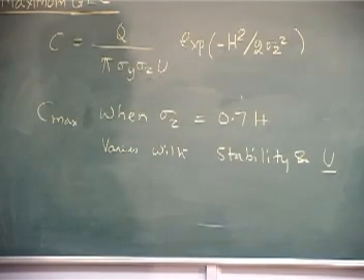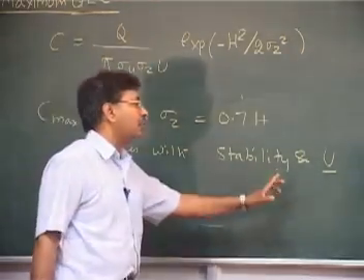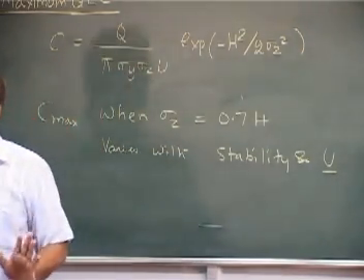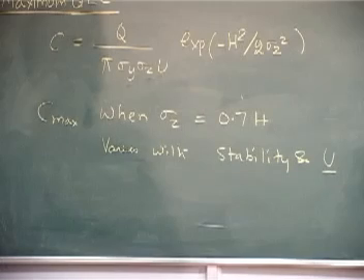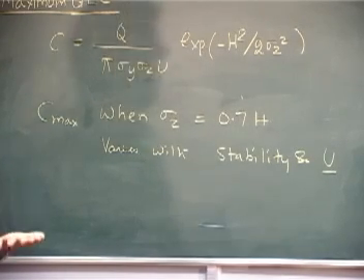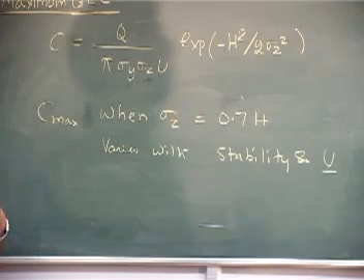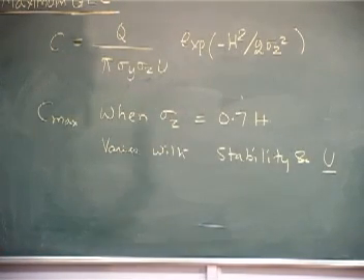If you have one value of stability and one value of u, you can say that under this situation this is the maximum impact. But stability will change hour to hour, as has been pointed out. The wind speed may change hour to hour. So our maximum concentration can be very variable depending on the stability and wind speed.